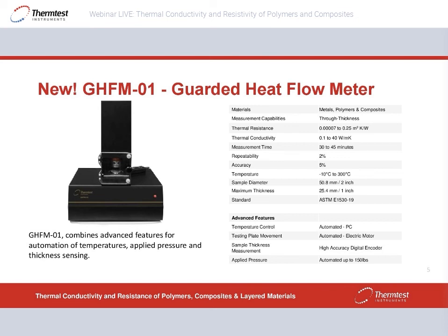So what makes this particular new device special? It combines advanced features of automation of temperature, applied pressure, and thickness sensing. So what does that mean? That means everything is controlled by the computer. The movement of the plate is electric. The sensing of thickness is through a digital encoder, which has a high accuracy. You can also set the applied pressure. So essentially you could set up an experiment to automate different temperature steps, different thickness steps, and different applied pressure. So we've really put a lot of development into automating much of those experimental parameters.